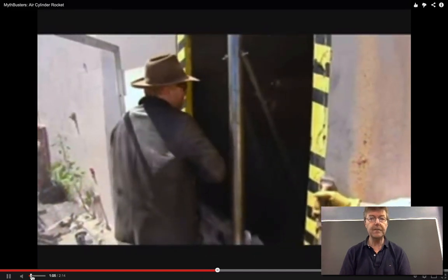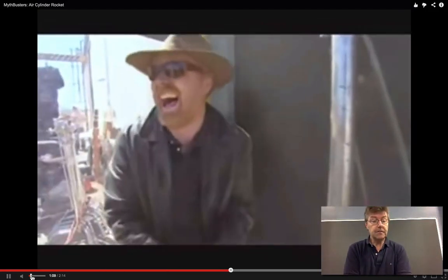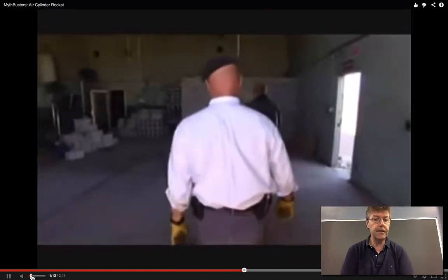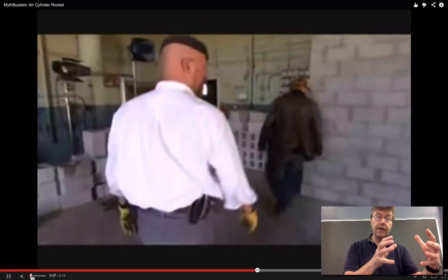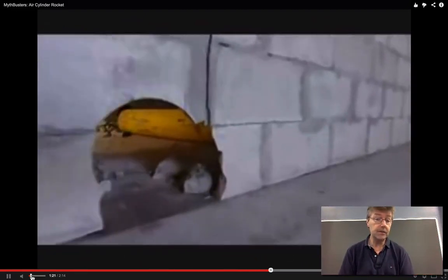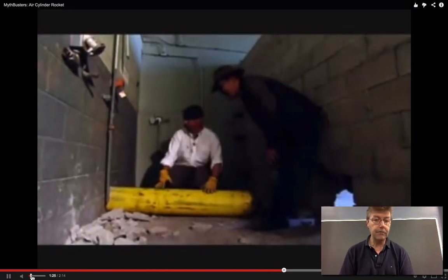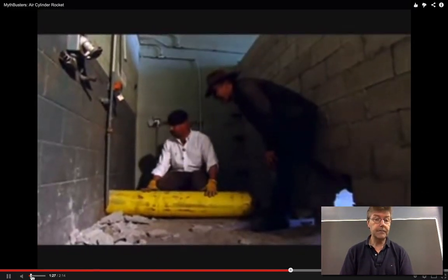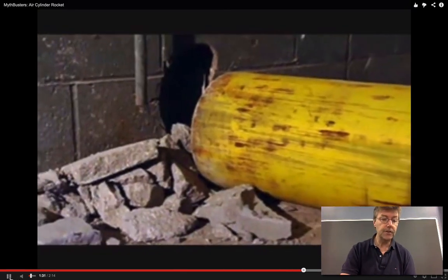The so-called sleeping giant, and all these safety admonitions for labs of not moving gas cylinders without properly putting this collar on the top, and securing them in place so they don't fall over relative to the bench, because this is what happens with them. They can fly across the lab, they can go through block walls, and be quite destructive. And so it is quite an interesting illustration of basically power.